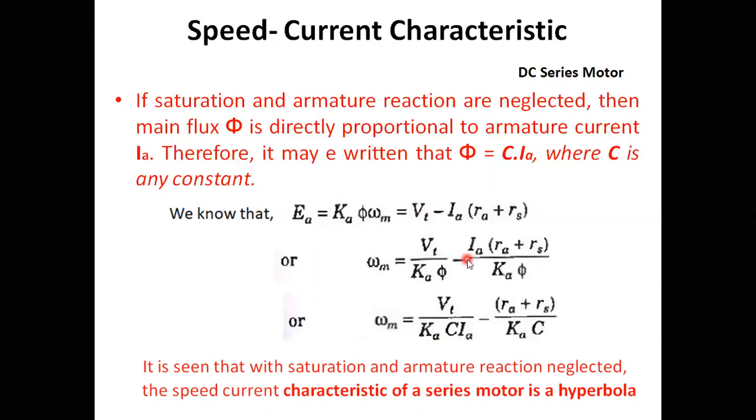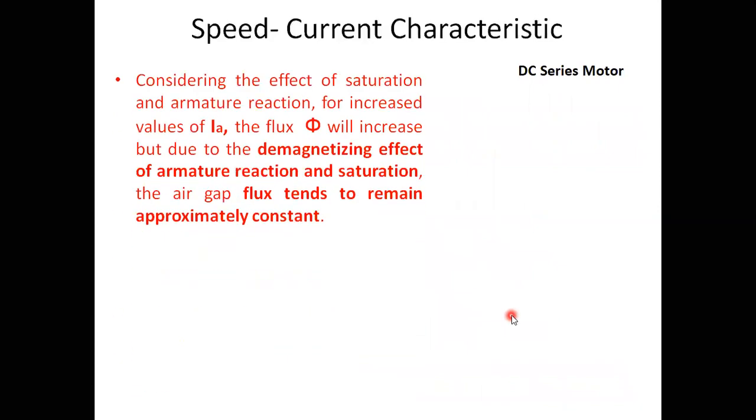So it is seen that with saturation and armature reaction neglected, the speed torque characteristics of series motor is the equation of a rectangular hyperbola.